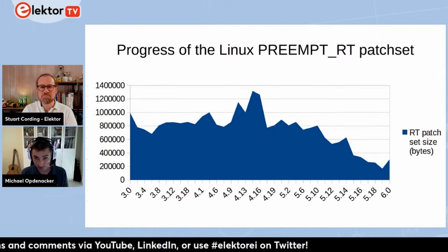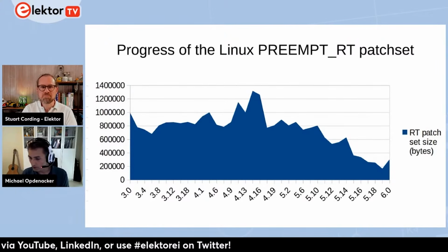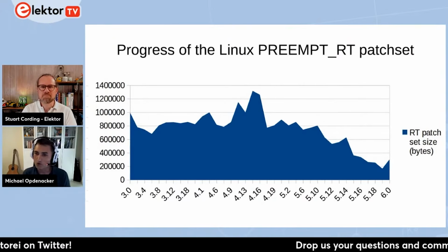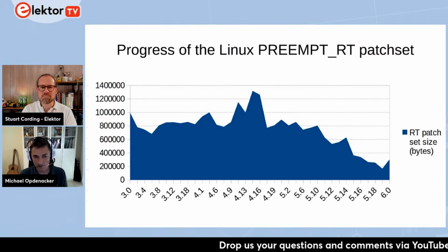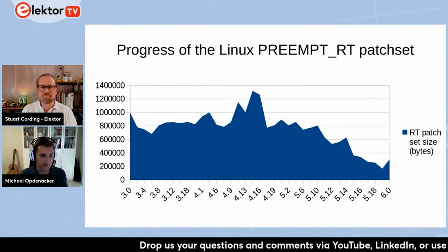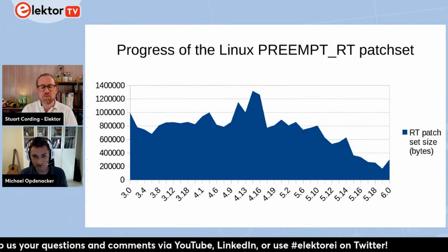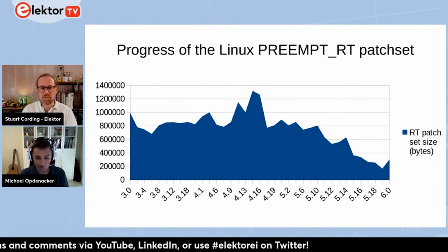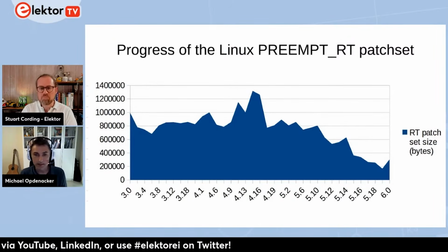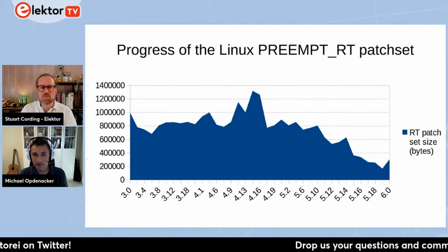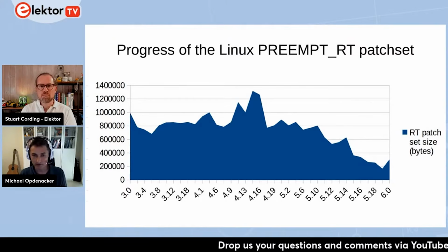With this, you can run tests, and for example on the BeagleBone, you can guarantee that your reaction time will always be within 70 microseconds or something like that. Wow, that's pretty good, I would say. Yeah, I mean, hopefully that's enough for your system. And yes, you've got this max response time to react to an event like an interrupt or things like that.